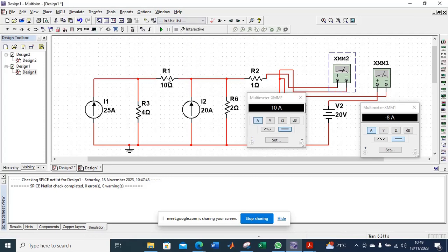Maybe let me go ahead and look at also how to get current in that branch. So I get my circuit, my ammeter I've selected, then I come and paste there. So remember, I need to connect it in series. Remember, current is flowing with the positive and ending with the negative. That's why I'm connecting my positive at the beginning and my negative at the end, because there is a potential drop.